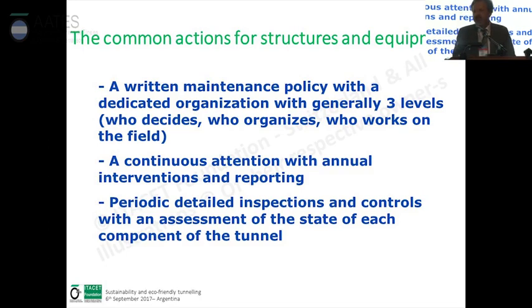So it has to be focused on the document. You have the necessity of a continuous attention with annual reports of what has been done during the year, what I've seen on the tunnel, what happens, and there is a written report every year on this. And also, the main new element, detailed inspection and controls with an assessment of the state of each component of the tunnel. If we have this kind of inspection, I will come back later on this inspection, I can be sure of what happened in my tunnel.